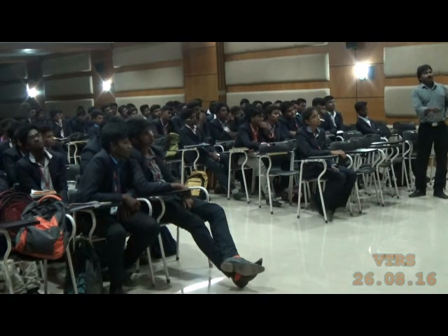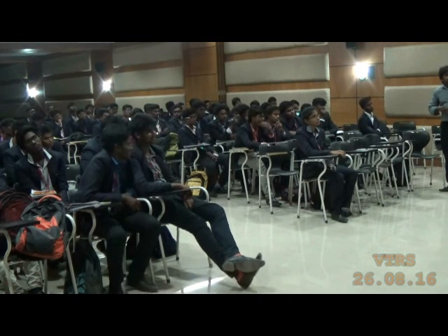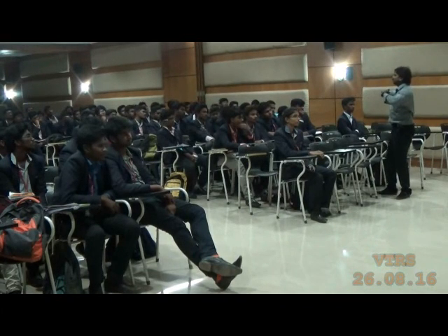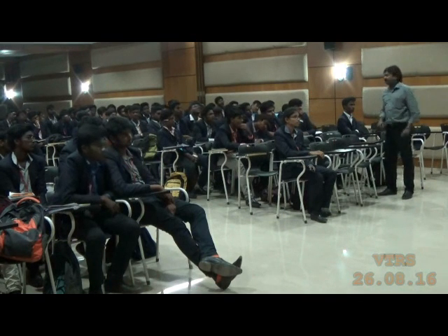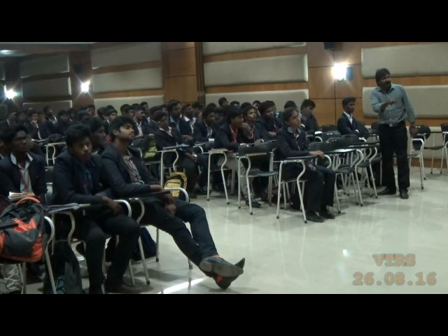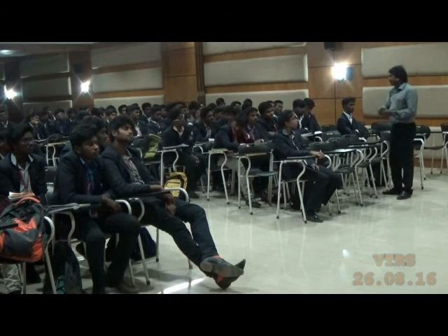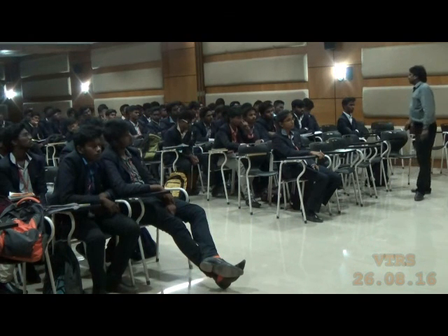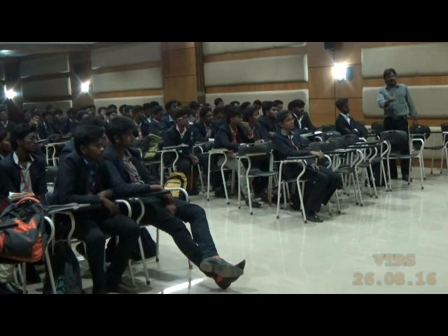So that's how you can see here. Please look at this image very closely. There are different regions. It is looking like a seashore, where the sea water will come and go inside. You can see layer by layer of material with different colors. That is what we call chevron marks. You see here a different kind of grains. Here some successive lines are there. Then you can see there will be a dot or different color over here. So with this, a person who has good knowledge in failure analysis can tell you the crack has started from here and it has traveled like this.